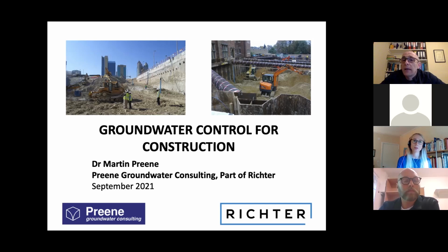So sometimes yes, there are regulations, and then of course the key thing is that everything has to be risk based. If you are doing a small dewatering job on a new development with no nearby buildings, the risk is low. But if you're doing something in a city centre or maybe near a contaminated site where you'd be worried about moving your pumping, causing the contamination to move, it's obviously more risky. So everything has to be risk-based in my view. And on the whole, the regulation in the UK does follow that approach.